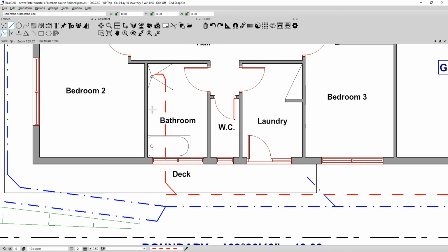We had the hand basin, which was here, comes into this direction, and again at 45, hold down the Control key, and I've got that line in, and we have the bath, which was a direct connection from here, and in fact that is also at 45, so hold down the Shift, forces it into that position, hold down the Control so I'm not snapping to the line, and click, and I'm very happy with the location of those items.